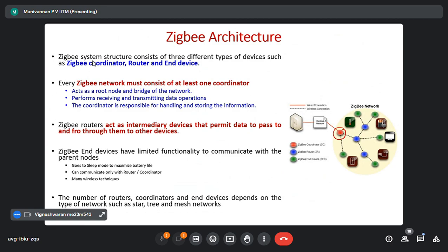Well, please note that this is your Zigbee device. The Zigbee device is only a receiver. Finally, it will be connected to a microcontroller. Data is coming here. Zigbee doesn't control directly. Its job is to receive data, decode it and send the data to a microcontroller. In the microcontroller, connect one output to the fan and another to another home device, for example, a washing machine.